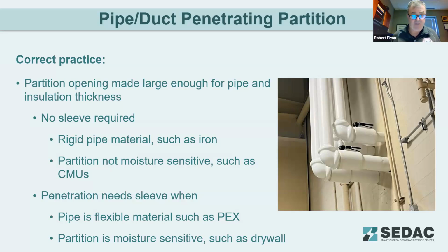Cleaner installation. However, depending on who you're talking to, the jurisdiction of putting CalSil in there is not by the mechanical contractor, but by the insulator or the insulator contractor. In the same respect, depending on the system itself, CalSil would be put on a higher heating system versus a chilled water system that might have urethane put in its place. Either way, that work, if done on a job, should be done by a trained, qualified person, and that person should be an insulator, in my humble opinion.